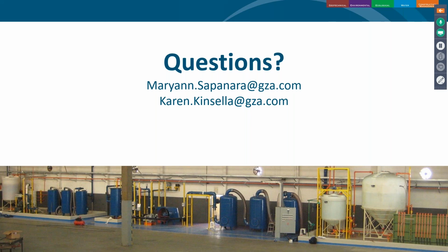So groundwater monitoring is part of the remedy. This comes down to the consent decree and, you know, previous owner, current owner, all that nonsense. But in general, I'm going to say no. Just let it go. No one's drinking it. No one's breathing it. All of the SSDSs have actually been decommissioned because water's down 20 feet below really tight soils, so there's no vapor intrusion issues to speak of. So just going to let it ride.